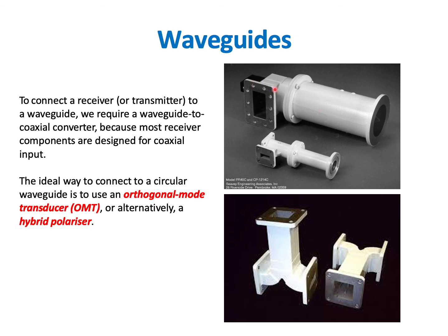So the light that comes in, the horizontally polarized light in this case, won't propagate through this vertical slit, but it will propagate through this horizontal slit. And the vertically polarized light that comes down will propagate through the vertical slit, but not the horizontal slit. So you split your light into two polarizations that way. Alternatively, the light coming in is most likely circularly polarized, and of course if it's circularly polarized, with the OMT you're splitting into two linear polarizations.